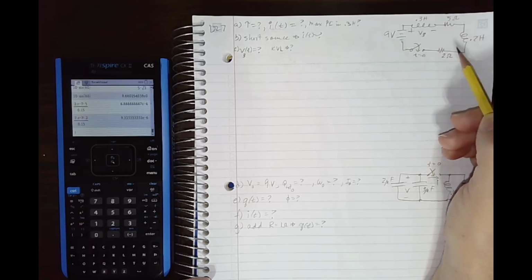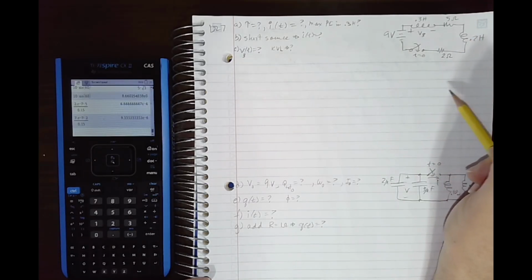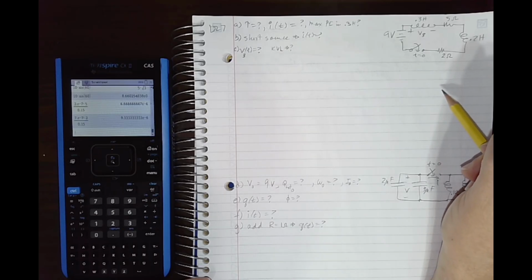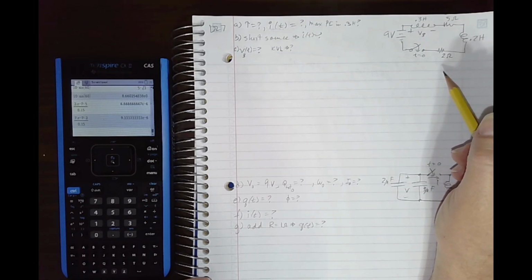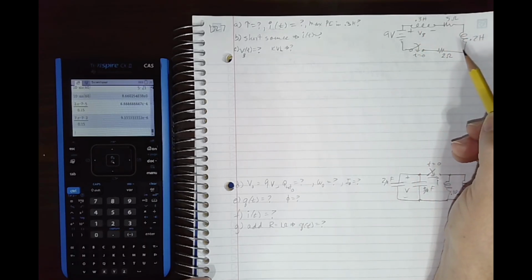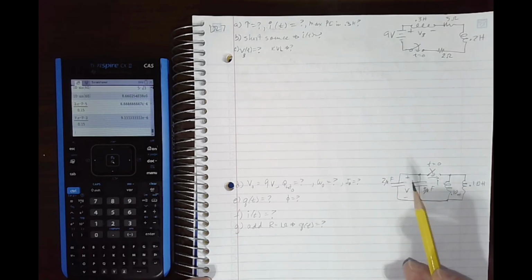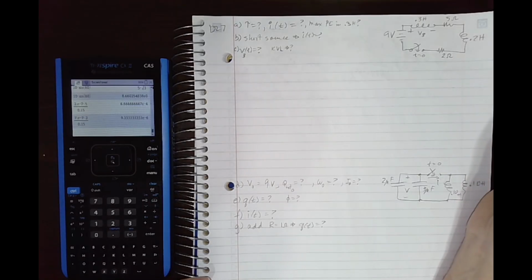Remember, when we have resistors in series, they just add up. When they're in parallel, we do the 1 over thing. And inductors act just like resistors in terms of how you combine them in series and parallel. So if we have two inductors in series, they just add together. Remember, capacitors, when we get to them, are the opposite. When capacitors are in parallel, they just add up, and when they're in series, we have to do the 1 over stuff.